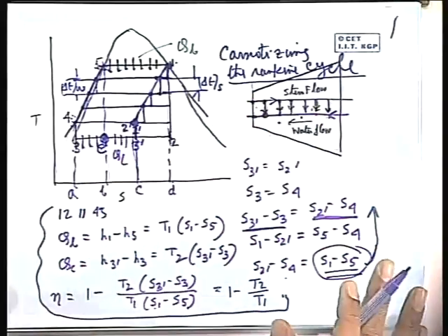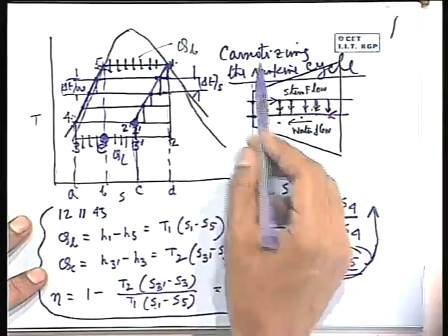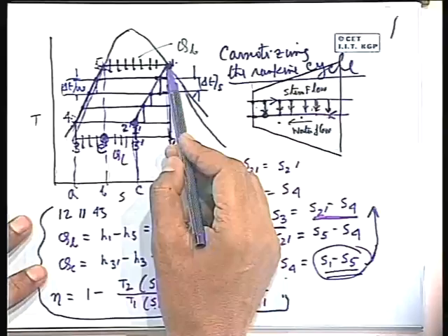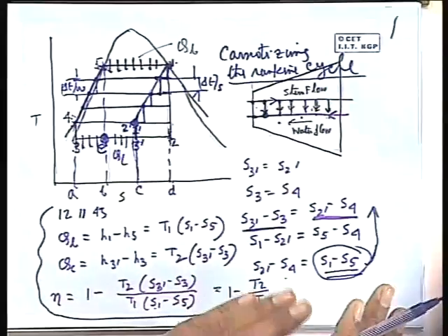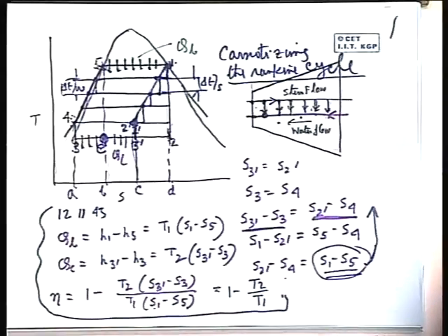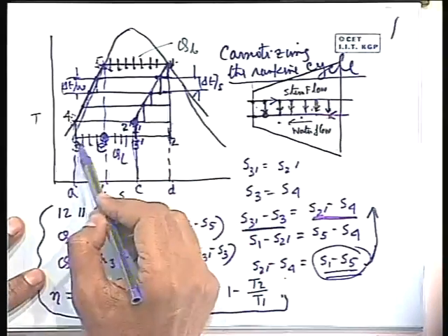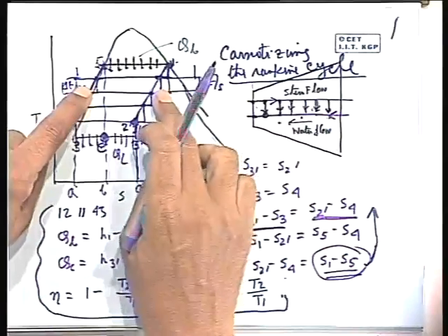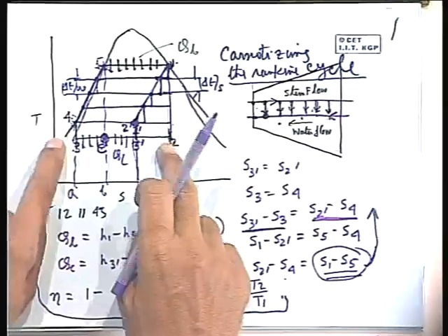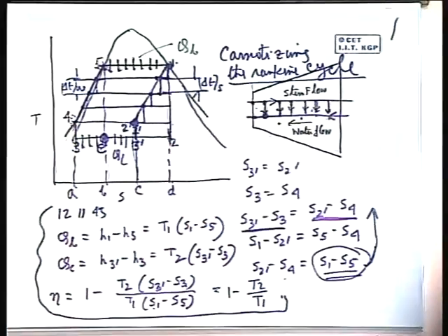So, in case of this ideal regeneration, if we could have made a reversible heat transfer, considering an infinitely long turbine and incorporating into the turbine the coil or the tube carrying the water, and considering there is a reversible heat transfer, so that the outlet temperature of the water is the inlet temperature of the turbine, and also the turbine inlet is not superheated. For a superheated Rankine cycle, you cannot Carnotize it. A superheated Rankine cycle can never be Carnotized, so the steam must be dry saturated. If all these conditions are fulfilled, which pertain to the ideal regenerative system, then a Rankine cycle 1, 2, 3, 4, 5 is Carnotized to 1, 2 dash, 3 dash, 3, 4, 5. This is known as Carnotizing the Rankine cycle, and for this ideal regenerative cycle we get the efficiency exactly equal to the Carnot cycle, though in fact the Carnot cycle cannot be implemented in practice.